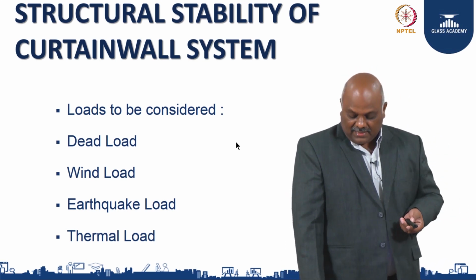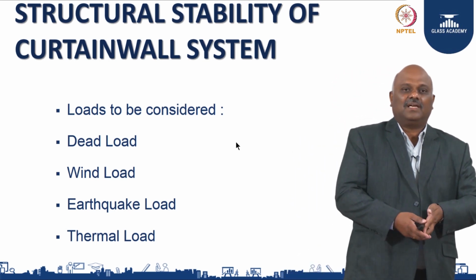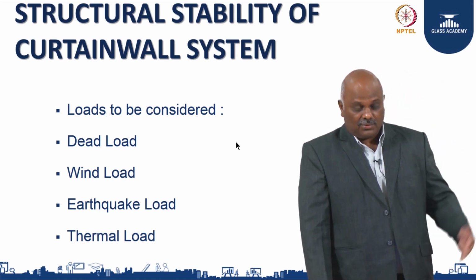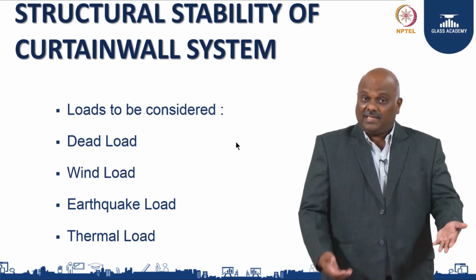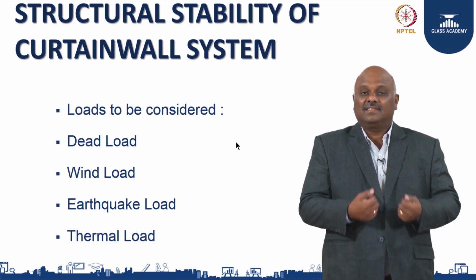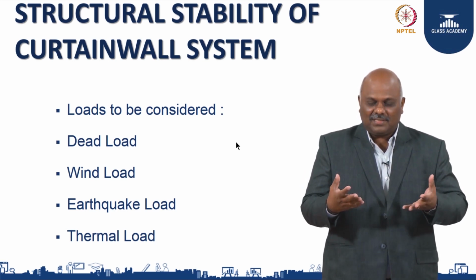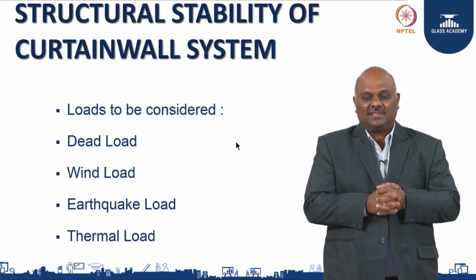Now, when I design a system, what should I consider? These are some of the loads you have here. Dead load is nothing other than its own weight. Wind load, of course, is the external force acting onto the system. Earthquake load, of course, we call seismic. Thermal load: the heat is not going to add weight to the system, but thermal load adds to the expandability of the system.